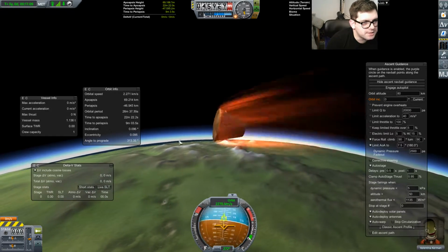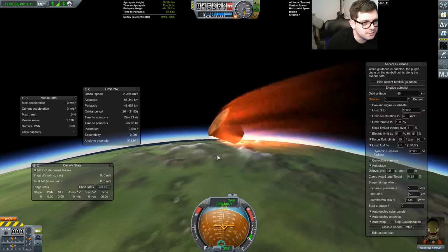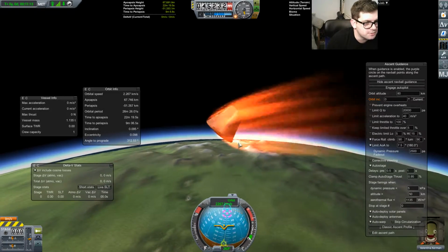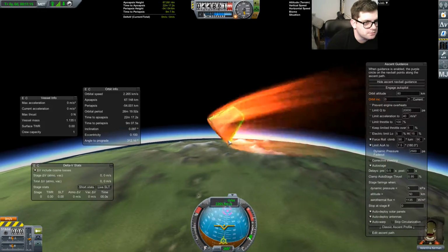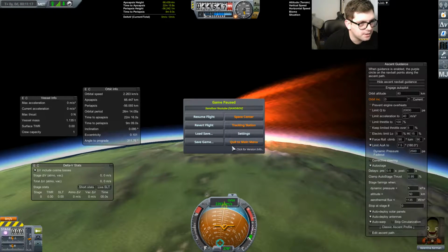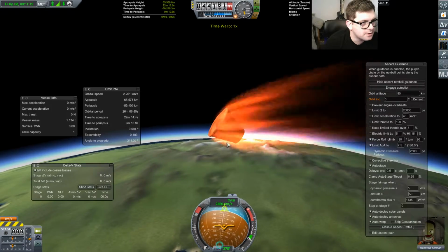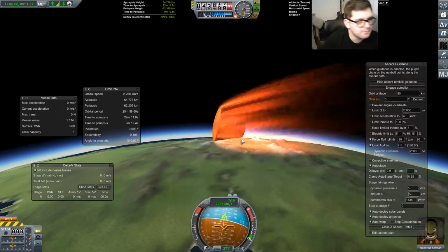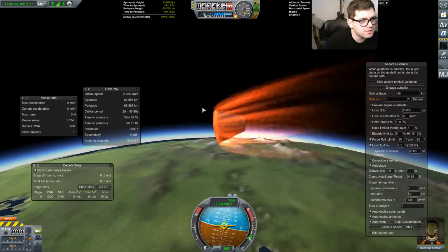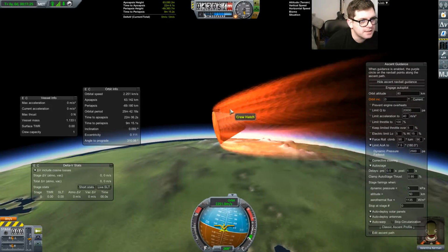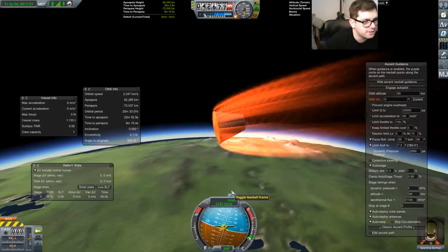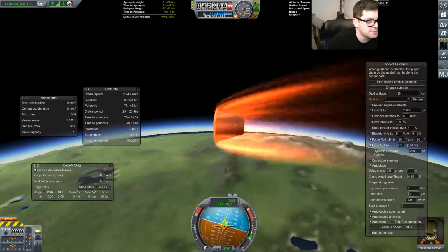And what happens is the airflow coming, say for instance, coming down this side, as it hits this edge, as it points outwards, as that comes out, there we go. Can't actually see that now. It actually hits that edge and pushes it back in. The same with this one, look, as it's hitting that edge, it's hitting the airflow, and the airflow is pushing it back in. So it is self-stabilizing.